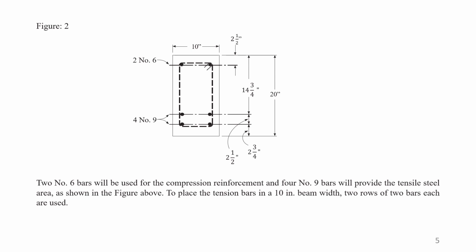From this bottom rod to the top rod, we have to keep a gap of 2.5 inches, and this is shown here. In your work, you also have to show these sorts of gaps and arrange the steel area like that.